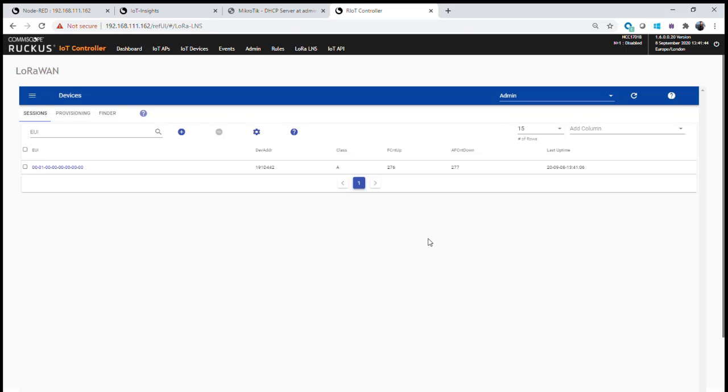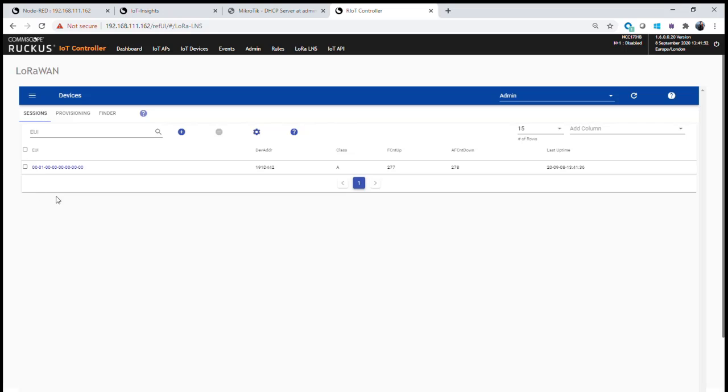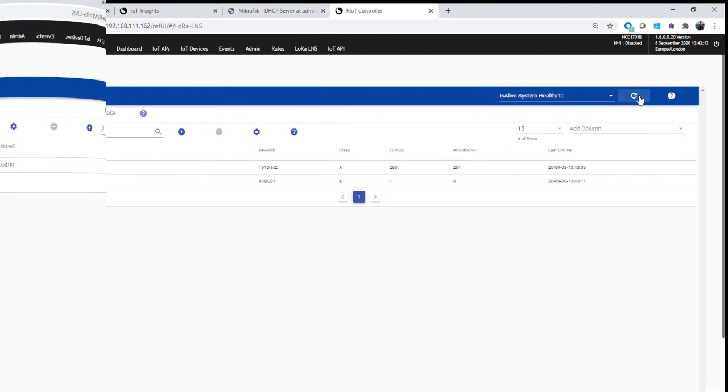And once those gateways are detected, it will provide its join EUI up to the LoRa network server and to the LoRa gateway, indicating that it's trying to join. The gateway will then in parallel communicate back to the sensor validating the keys and providing a secure connection between the sensor and the LoRa network server using the gateway as a transparent interface. And there we go.